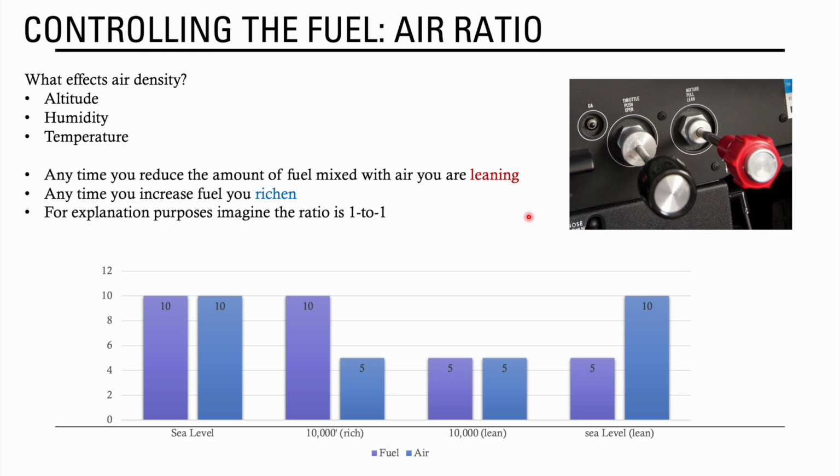It brings up all of the cylinder temperatures and identifies which one's the hottest, and then you keep leaning it until it reaches a peak in temperature, and you operate a little bit cooler than that peak. The system will tell you, which is kind of cool. Otherwise, there are gauges that tell you exhaust gas temperatures or cylinder head temperatures. You could do it that way.